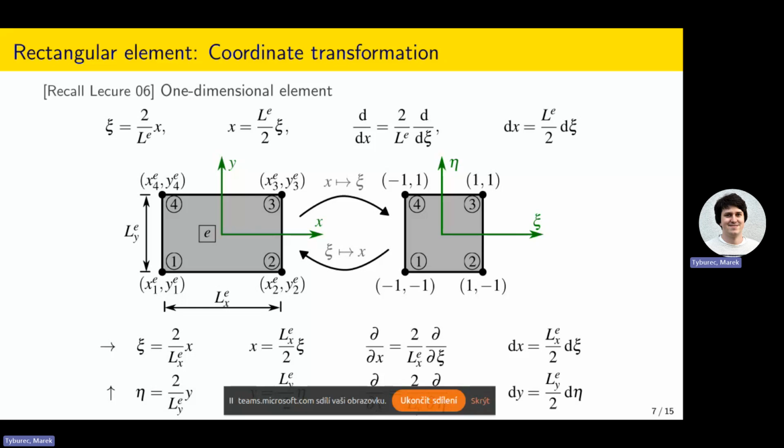For these functions, you can check that they essentially match the setting we have in this figure and the ordering of the nodes that we have here. Okay, so those are the shape functions. But we did this kind of substitution or mapping, so that we modify the domain of the element from the xy system to the psi and eta system.